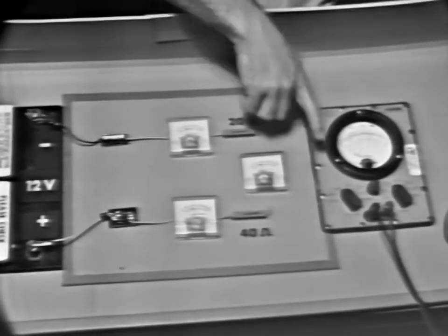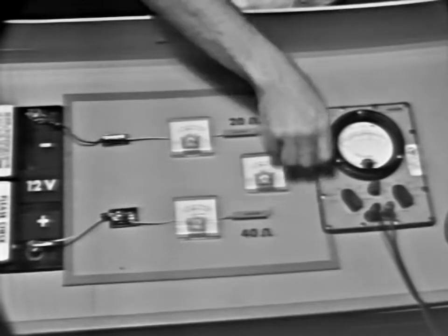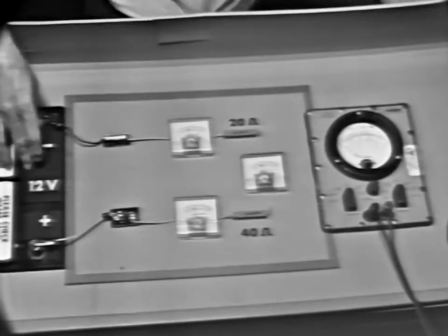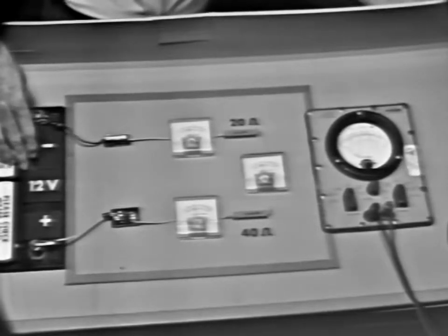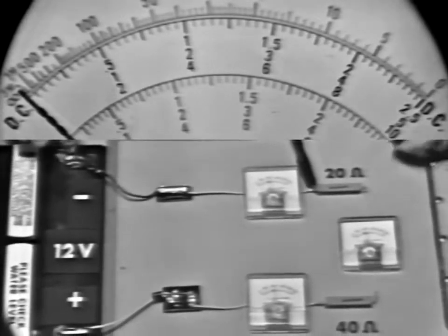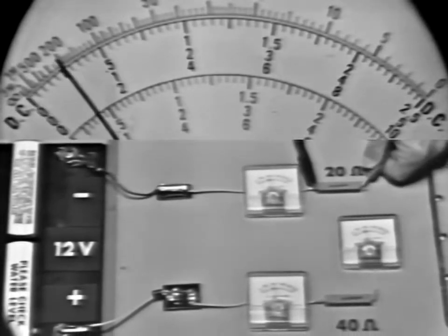Let's use the PSM6 and check this out. We'll set the PSM6 to the DCV function, and we'll use a range of 50. We'll use 50 since the applied voltage is 12 volts, so we're being safe. Now remember, we must observe polarity. So I'll place the negative lead here, next to the negative terminal of the power source, and the positive lead